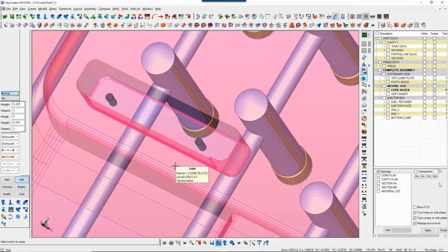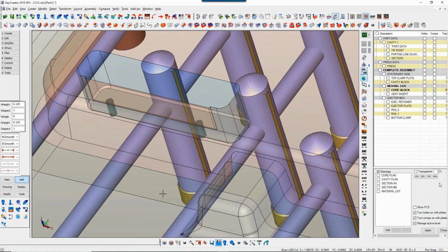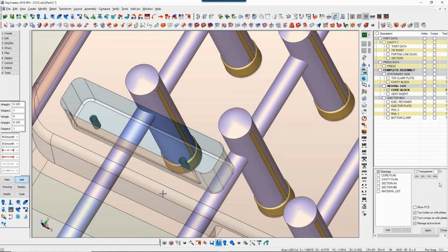You see how the hole color changes, right? That's because the configuration that I have for my holes is to use that color if it's a metric tapped hole. And then, of course, clearance holes and your critical reamed holes and things like that all can have their own colors. This will allow you to utilize feature recognition tools in your CNC machines on your floor much, much more efficiently. Because everything's working off one central config file, if you have 10 different designers doing 10 different things, your feature recognition on your shop floor isn't going to work really well. But because everybody's working off the same config file, all your holes will be exactly identical every time they go to the shop floor, speeding up your manufacturing.